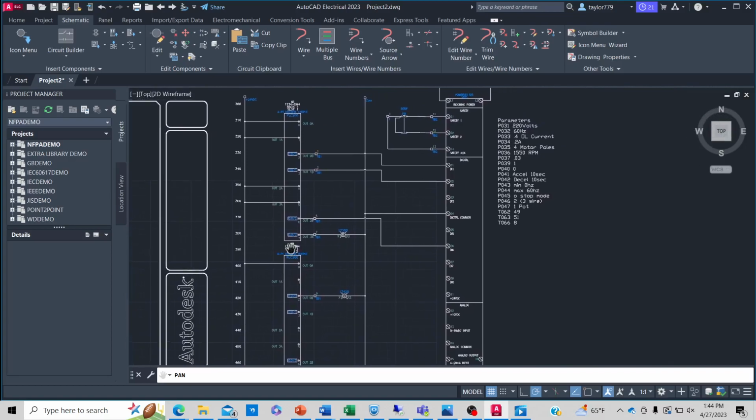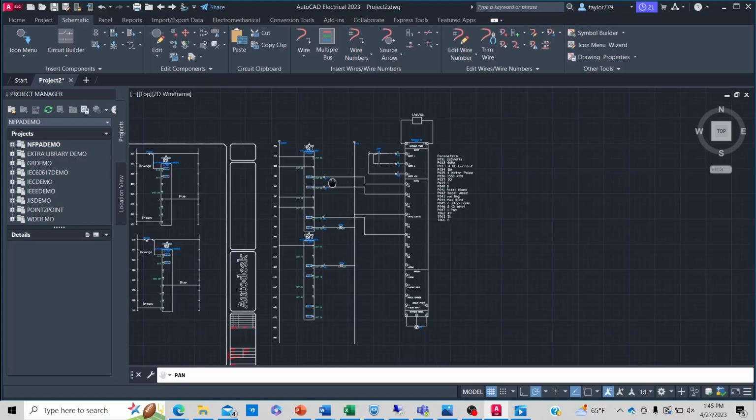And then here you have my VFD setup. So this shows my physical setup, but right now I'm not using it because I'm using it over Ethernet because it's a lot easier to change the settings in your frequency drive instead of going through all those parameters that you don't even know. This shows the label of each parameter and its value, and you can change it. But I also have this set up as well.